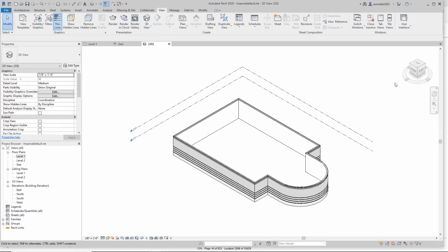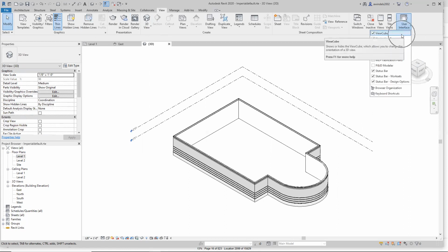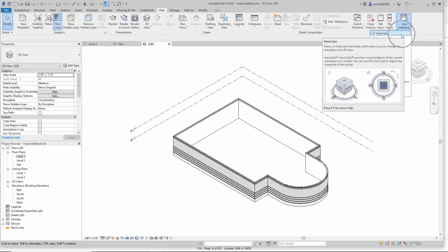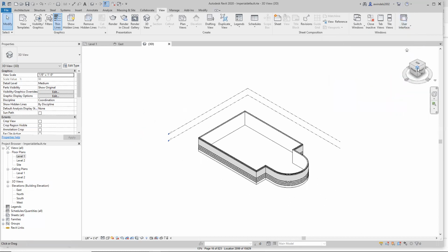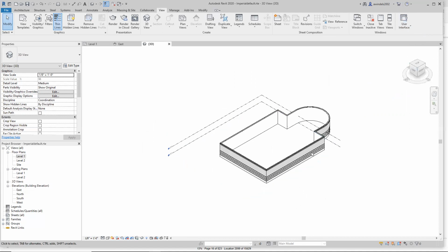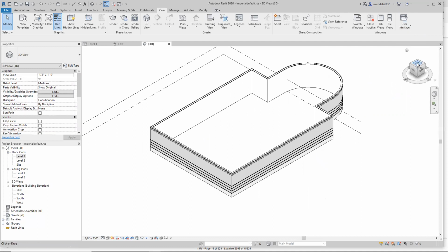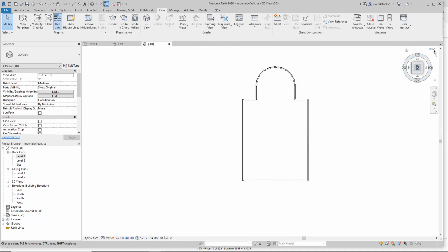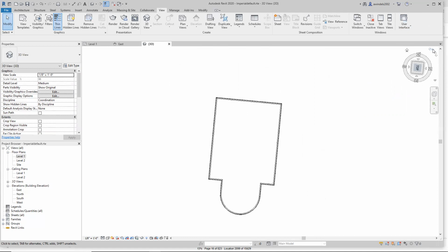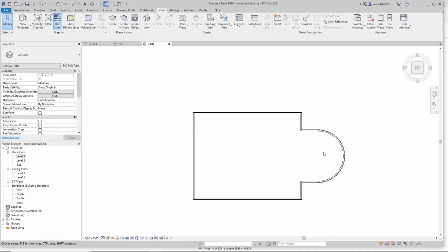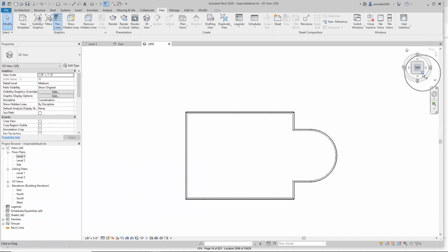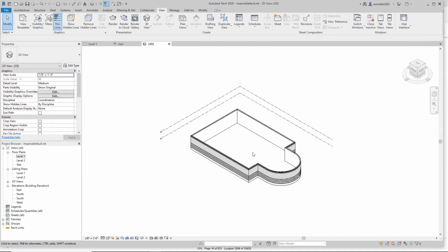That's our 3D view. We have our view cube over here. That can be turned on and off here. Now it's available because I'm in a 3D view, the view cube. We're able to go to very specific isometric views. Building. Back to the top, still 3D. Top, north, east, south, rotating like this. North usually is north. That's usually a good way to keep it, but we can go back to an isometric view.